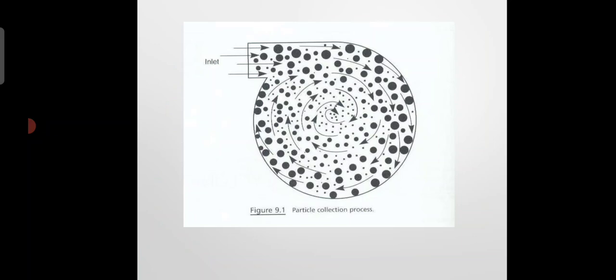So this image shows the cross section of the cyclone separator. The arrow mark indicates the movement of the flue gas, thereby the particulate matter. You can see near the center there are more smaller diameter particles, and towards the outer section we can see larger diameter particles. Larger diameter particles can't move along the circular motion due to their weight, and hence they settle down, whereas the smaller size particles, since their mass is very low, move up with the gas in the spiral motion and escape from the cyclone separator.